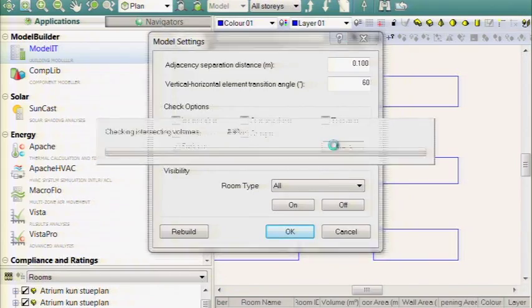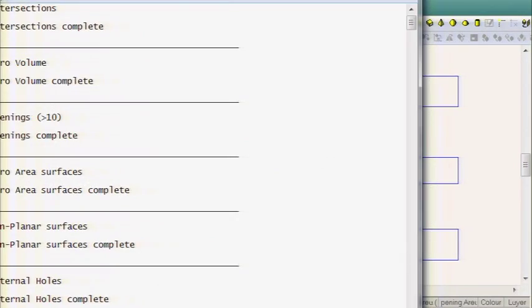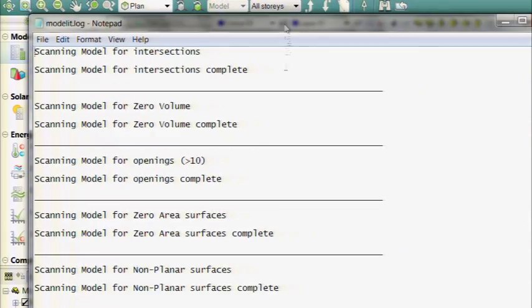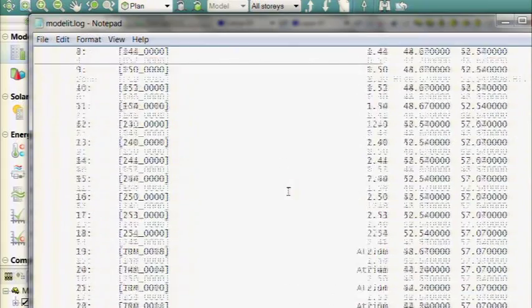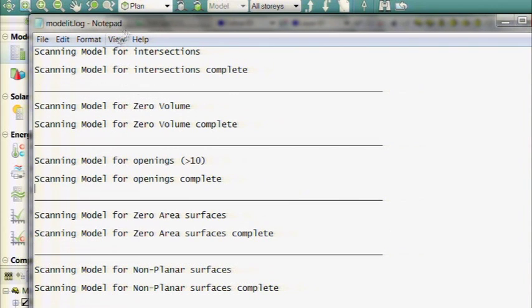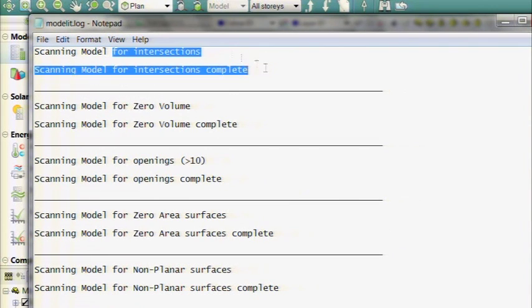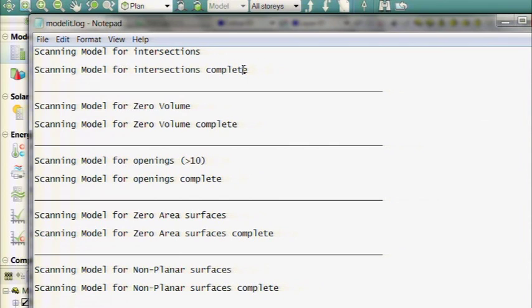But you can do a check here. And it'll show up very big. But it's going to go through your whole model and say, are there any intersections between my spaces? For a very large Revit model, I bet there probably are. In this case, this one works out.